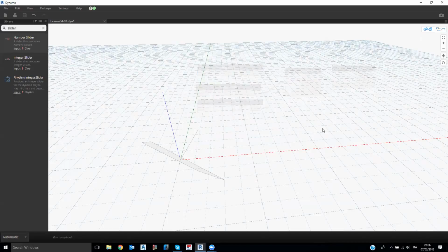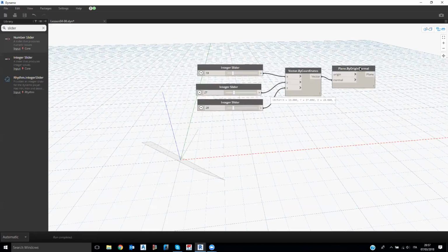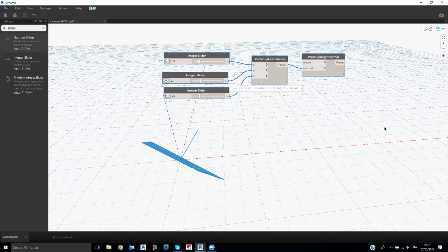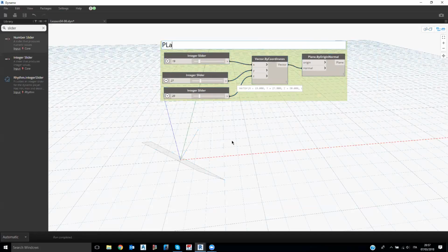And I'm going to start now an example of this. So this technique that I'm going to show you now is always used when you have a section that you want to loft around a path, or you just want to copy along a path. So let's say that this is the creation of a plane. So Control G, and this is plane creation.